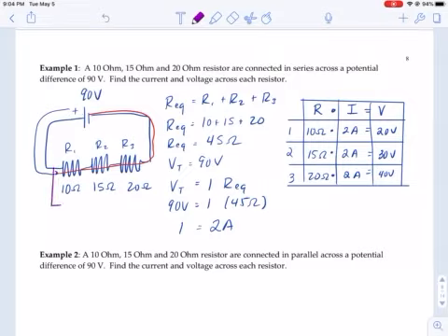And if I were to actually take voltmeters and put them across these resistors, I would find that the first one measured 20 volts. And what that means is that when these charges come through the wire, this 20 volts is 20 joules per coulomb.